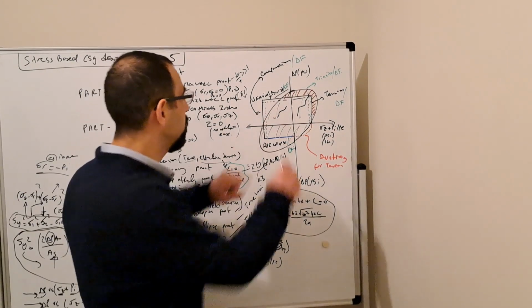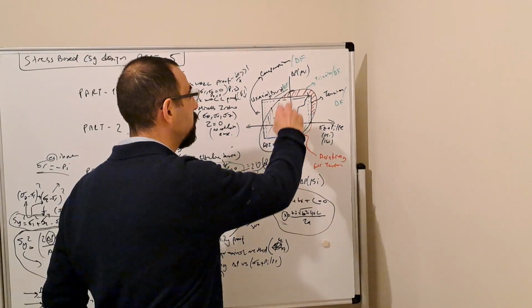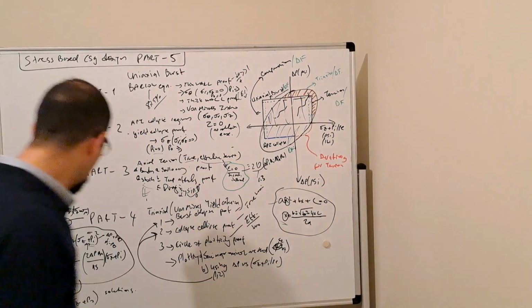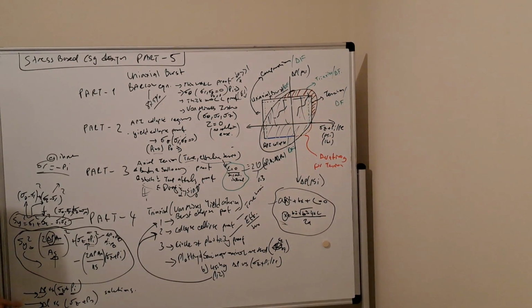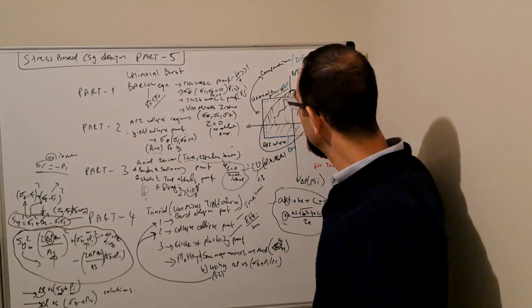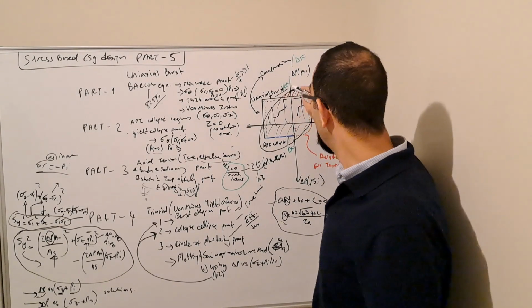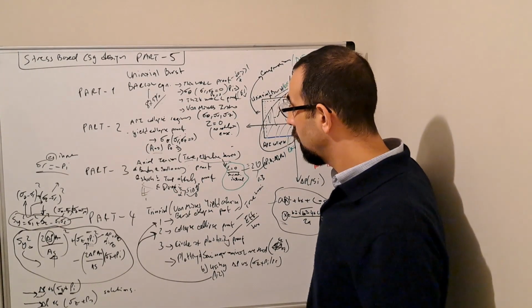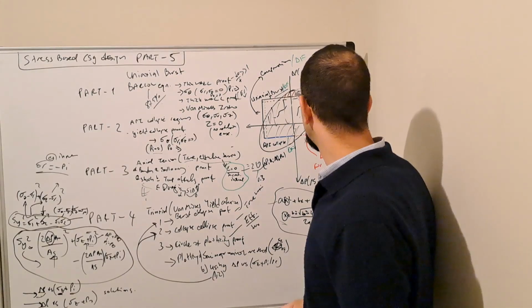That was the burst ellipse, which is the upper side, and those two solutions gave us the exact solution, the exact root for delta p, which means delta p on the lower side is the collapse rating, and delta p on the upper side is the burst rating.